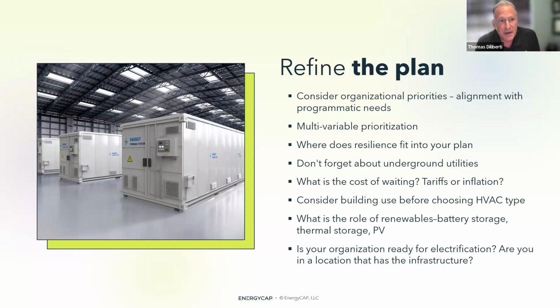And my supposition here, or my statement, is as you consider your buildings and how you manage them, also think about how you design them. If you have a building where you know you're going to have people in only one part of the building, you might choose, in this example I'm talking about that has a chiller, maybe in one quadrant of the building or one area of the building, you put in a rooftop unit. Maybe the chiller and the piping only runs through three-quarters of the building, and the last quarter of the building is a rooftop unit or two, because you know you can control it independently for energy conservation reasons, and you also will get more comfort because the rooftop units will be working the way they're designed, rather than a chiller system trying to serve a building that's got very few occupants in it.